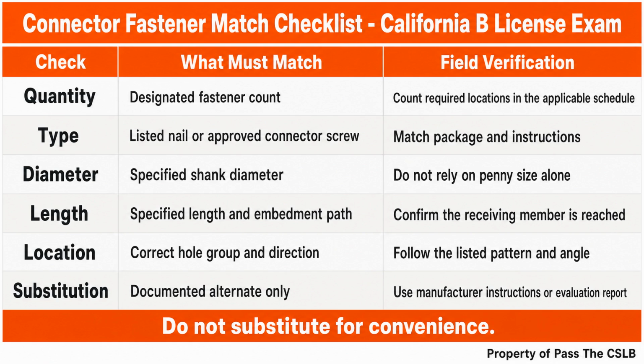Here is the physical connection. Shear acts across the fastener shank. A thinner shank has less cross-sectional area. That does not let me calculate a connector's allowable load from diameter alone because the tested assembly and evaluation report control the rating. It does explain why a visually similar thinner nail is not a casual equivalent.